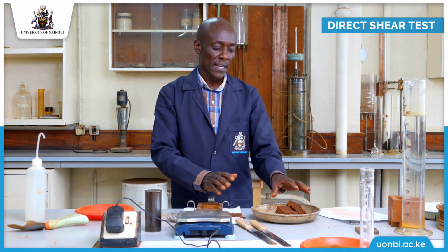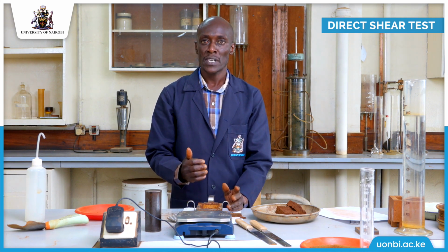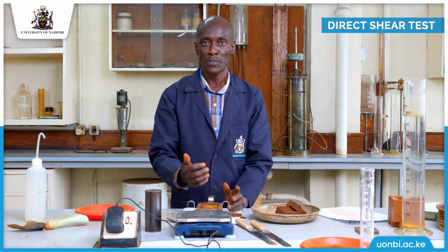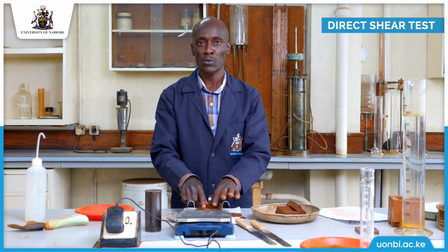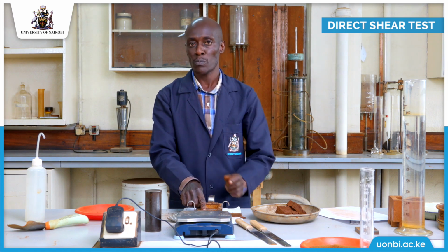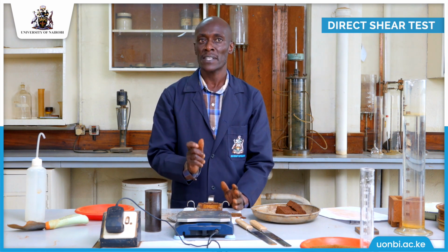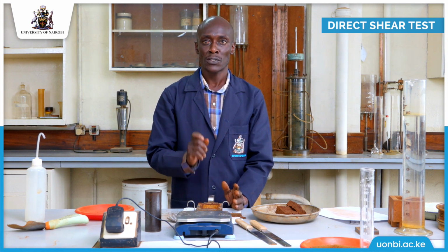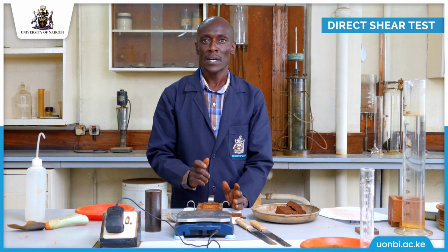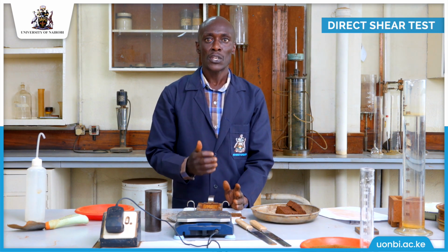After removing that sample which has already sheared, the next thing that you are supposed to do is you repeat the same procedure by again measuring the soil sample that is required to fill this mold, also the amount of water that is required to mix with that soil sample. Then you repeat the same process again, but this time round you change the masses. So the first load was 32.2, the next one will be 68.9. When again that shears, you do the third one with 105 kgs.